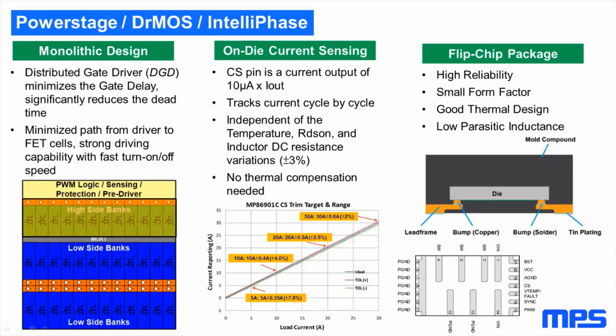This is done, and you should see it in the picture below, by having many single drivers that drive parts of each MOSFET. Each MOSFET consists of many, let's say, simple, small MOSFET cells, and they are all set in parallel. And some of them have a dedicated driver. And the big advantage of this is that we can have a short dead time and short delay times.